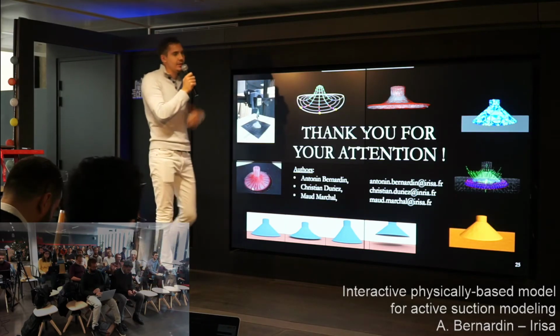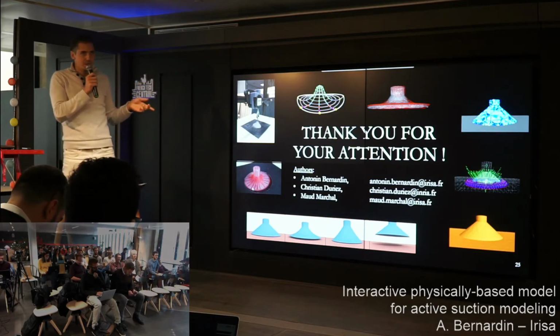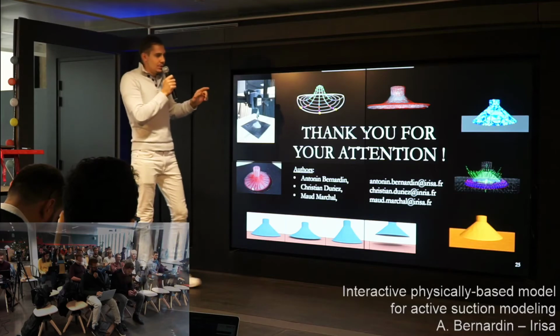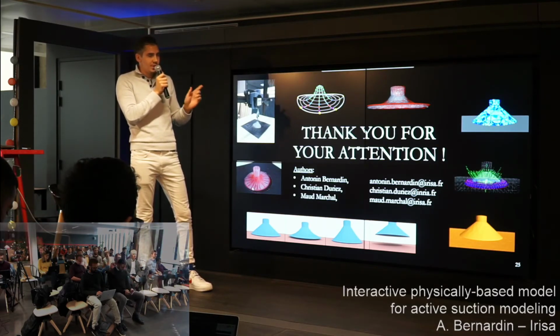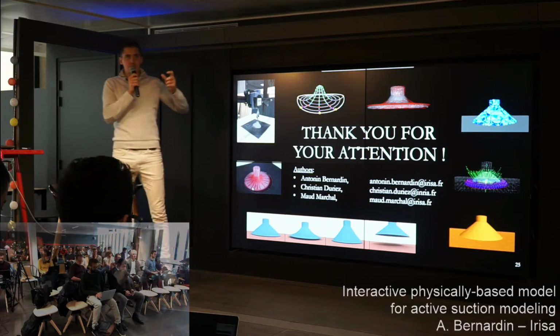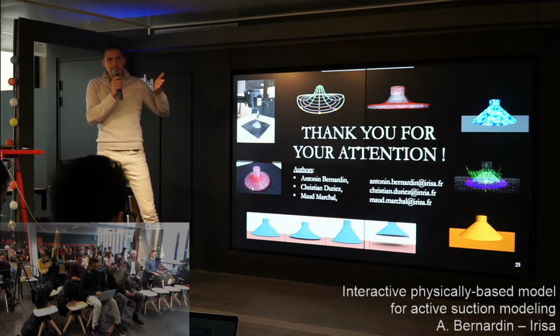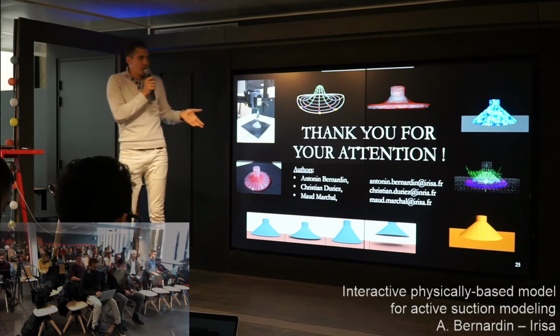Actually, I can quickly explain the oscillations we saw in the video. The points which are on the collision mesh and which are close to the seal oscillate between two states. For one time step, it is a contact point, and for the next time step, it will maybe become a pressure constraint.